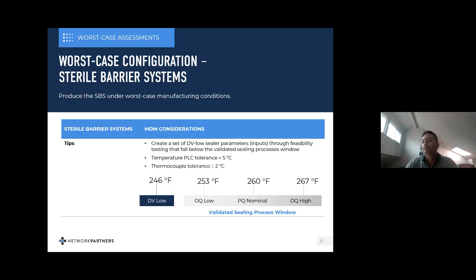Okay, for taking peel samples during PQ, you advocated random locations. Why not take 1/3 from left, 1/3 from center, and 1/3 from right? Are both approaches valid? Yeah, you can do it any way you want. I like to say just randomly take a peel sample from, let's take the MDM seal, our final seal. I just say randomly take a sample along that.